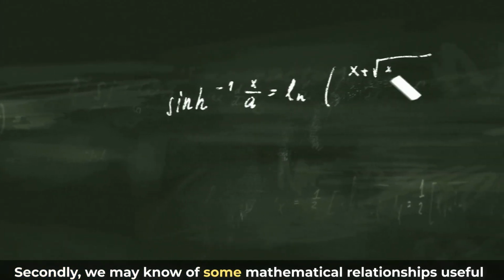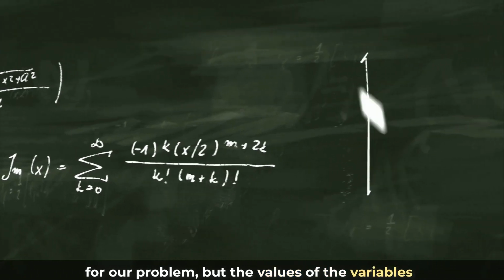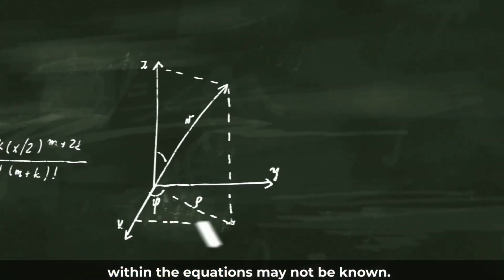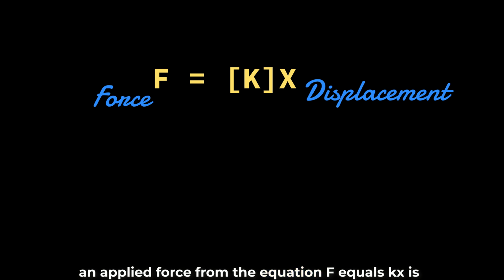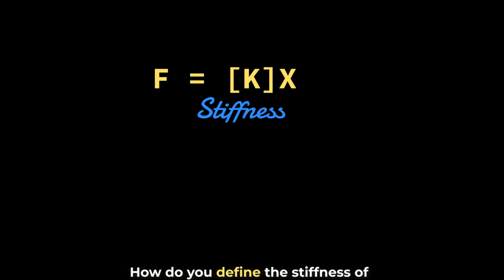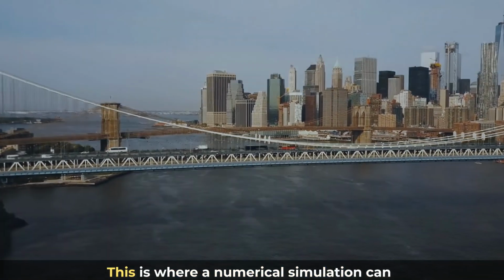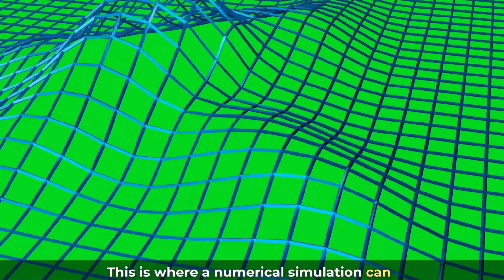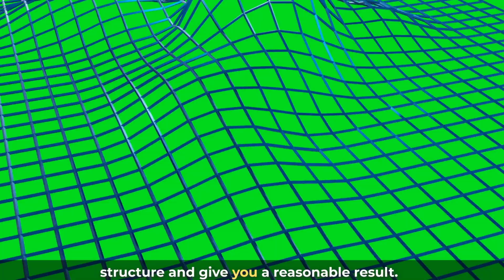Secondly, we may know of some mathematical relationships useful for our problem, but the values of the variables within the equations may not be known. For example, obtaining the value of a displacement due to an applied force from the equation F equals kx is only possible if we know the stiffness for our structure. How do you define the stiffness of a car, a building, or a bridge? This is where a numerical solution can come in, approximate the stiffness of the structure, and give you a reasonable result.